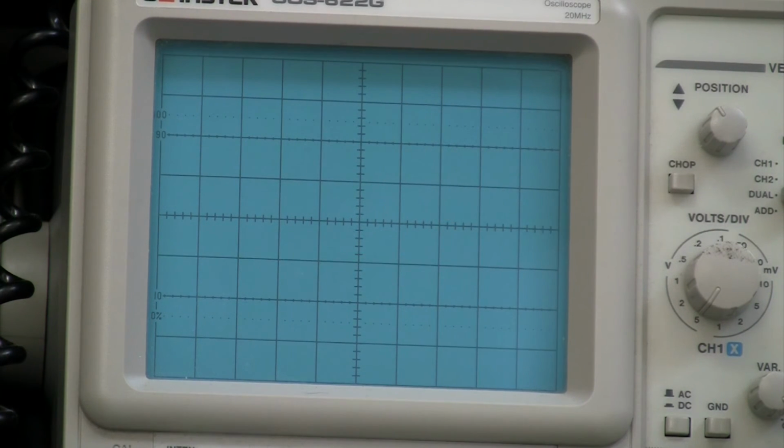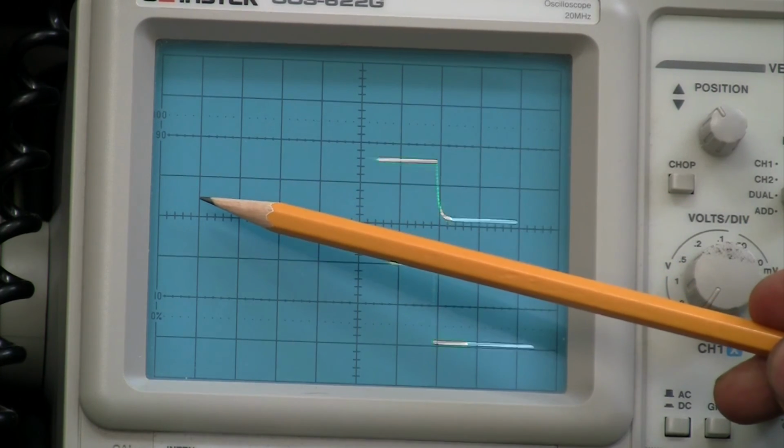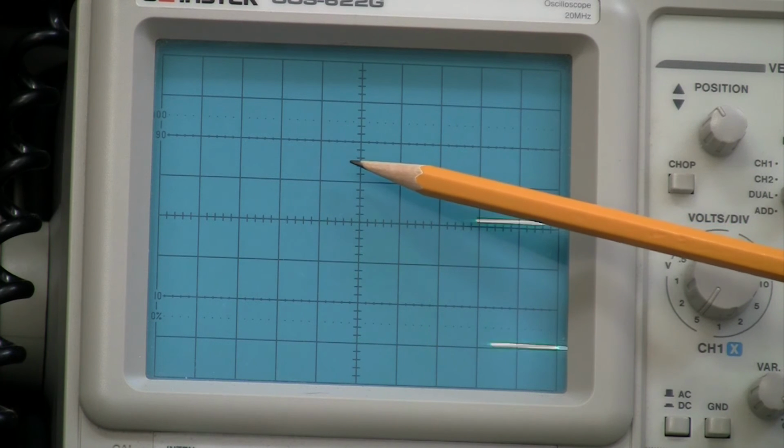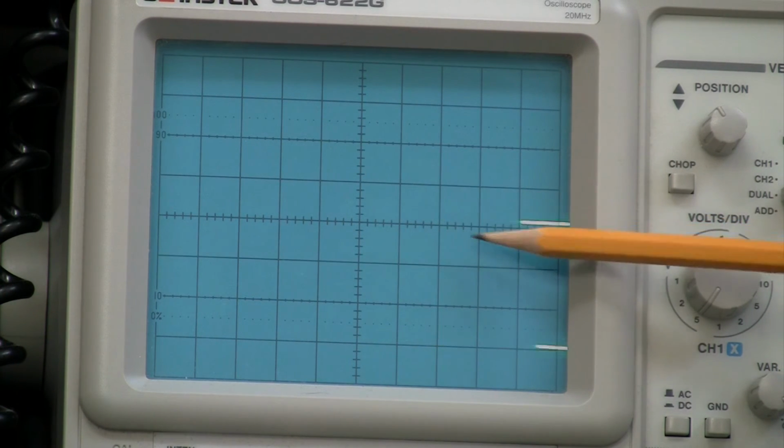Let me change my scale so we can see this a little more closely. Now I have an attack phase that's concave, goes up to 5 volts. There doesn't seem to be any decay. I'll turn the sustain level down on the envelope generator to kind of reinstate the decay phase here. And there it is. So now I have an attack phase that's concave, kind of a hold phase, a decay phase, a sustain level, and a release level.